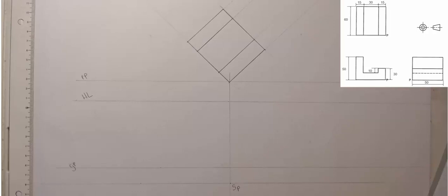Right, then they say the right view is on the ground plane, well to the right side of the station point. So the right view is going to be somewhere here. Okay. So now the first thing that we need to do before drawing the right view and the front view, we need to construct lines at 45 degrees and 135 degrees respectively from the station point to cut the picture plane as shown.